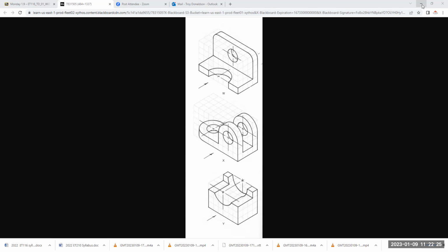And any arcs I worry about later. I get some straight lines in, right? But that upper arc, I'll do that later. So I'm just going to box it all in. 2, 4, 6, 8 inches this way. Just aiming and putting in a distance. Looks like the bottom is 2 inches tall. So maybe I jump over here and go up 2. And then bring it in.